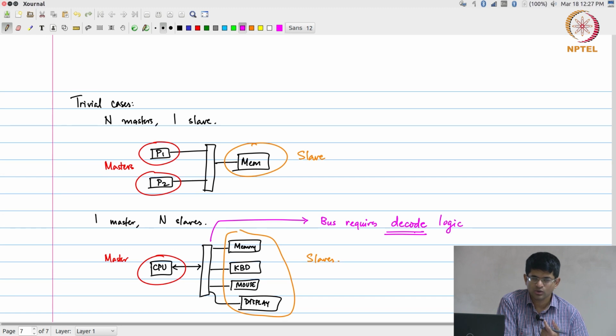Okay. So, like we discussed in the previous class, memory mapping essentially means that address can now be used in order to indicate which of the peripherals I am trying to talk to. The bus looks at the address and decodes it. This is sort of an anthropomorphic way of looking at it. There's nothing sitting on the bus that's actually looking at it. It's just a set of gates ANDing things together and deciding, okay, is there a match or not, right?